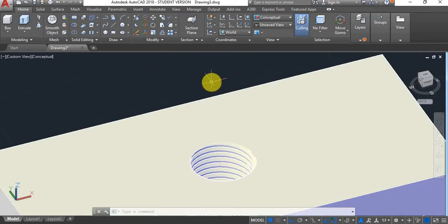Again, as I said, for a 3D model, it's best to just leave it like this, and then on your 2D drawings you can indicate the drill size, the tolerance, what bolt and what internal and external thread you're using for each.